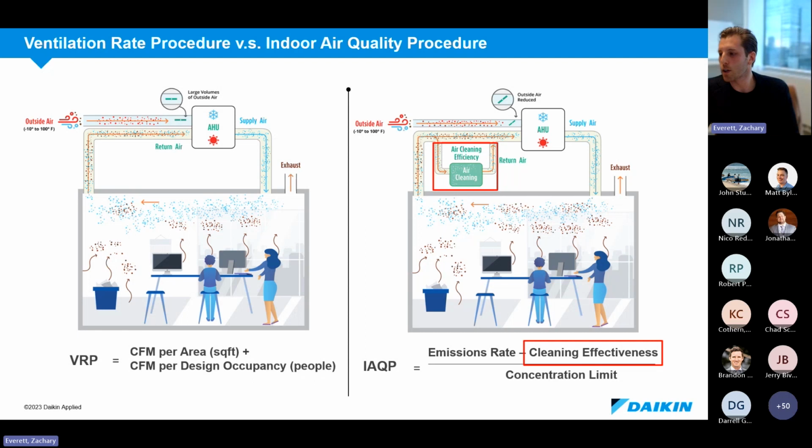And the idea there is that we're going to be displacing some of the existing air and exhausting from toilets and variable exhaust from kitchens and everything else. We're going to be exhausting some of those contaminants out. So this is dilution ventilation. So the kind of mantra you may have heard in the past is the solution to pollution is dilution. That has been how we've designed for the vast majority of the history of ventilation code.